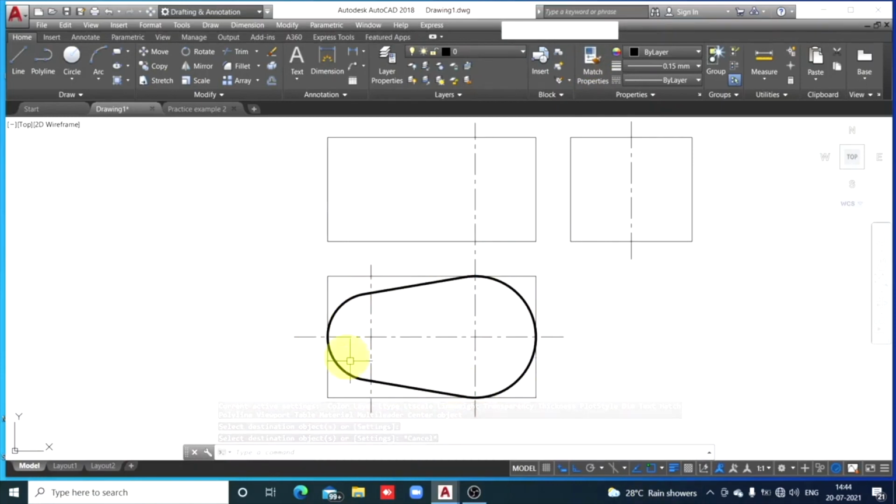Now this is a base plate. Dimensions you get in the top view are length and width, vertically. Height appears in the front view and in the side view. And it is a base plate. So from the base you are going to measure a height of 20 millimeters. Identify the base, and from the base check that green rectangle there. Click it, because from the base you are going to measure 20 millimeters. You want a height of 20 millimeters.